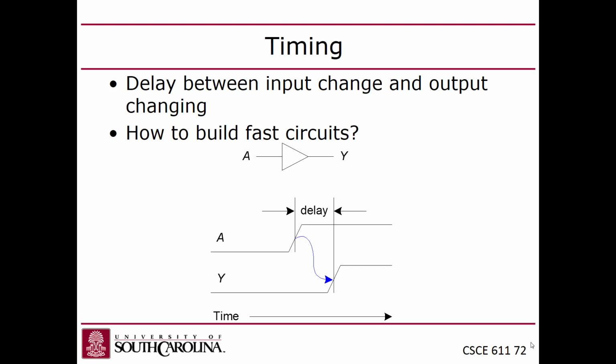That's the product, resistance times capacitance. The time it takes to charge up a capacitor is just the resistance times the capacitance. Is that easy? Yeah, it's that easy. It actually works out that way. This is the capacitance in farads and the resistance in ohms. You multiply them and you get charge time: how long it takes to charge them up. You guys with me?